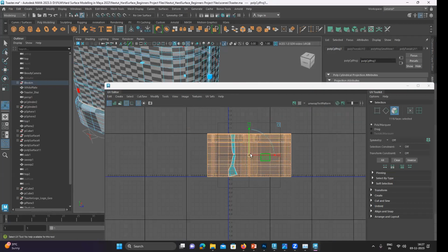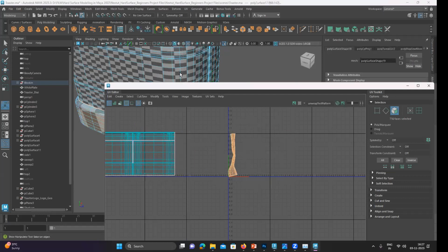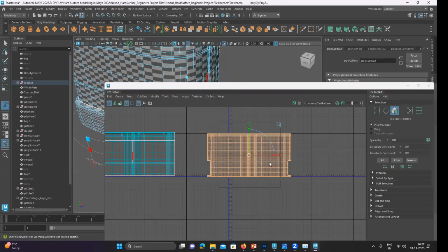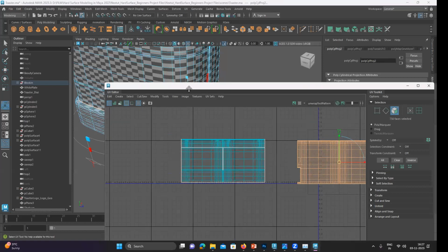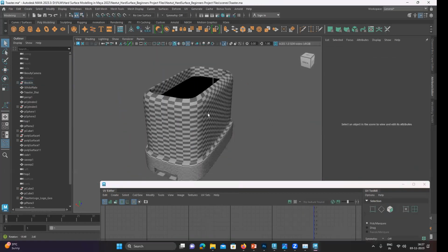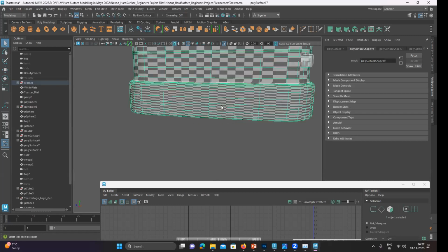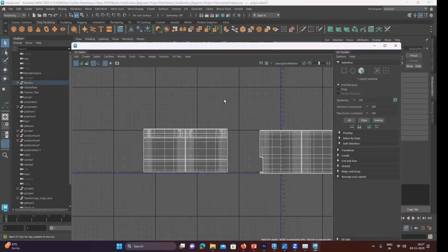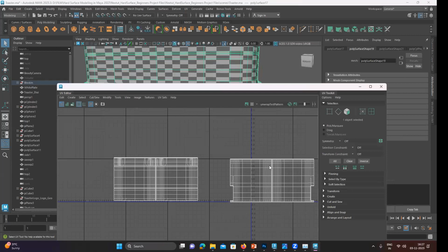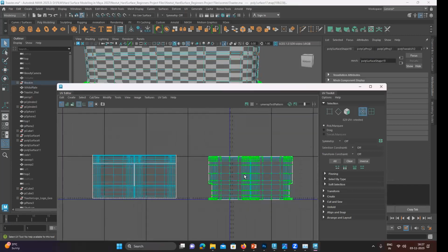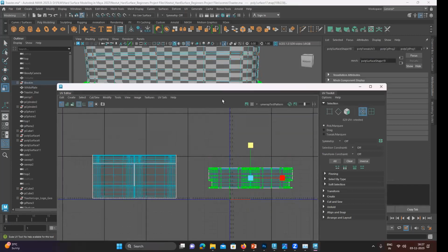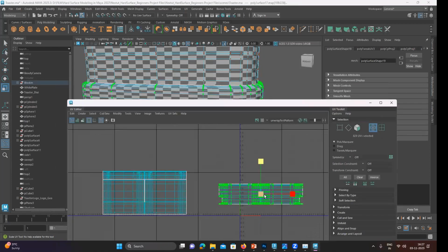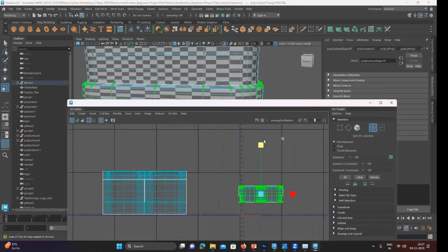Once it is done, select this face and you can use your traditional cylindrical mapping. Okay, select these UVs, cylindrical map, done. So this checker method is also useful. That means you can adjust the texture scales I'm talking about. So UVs, and obviously you have to check this as well, right?